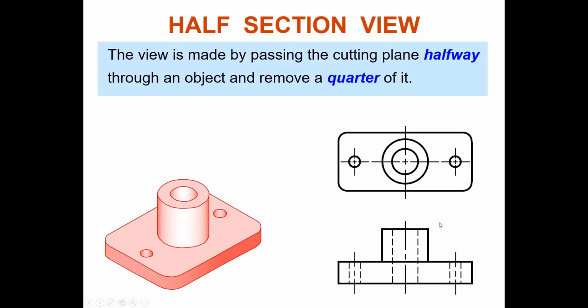Maybe some of you misunderstood. So do I make a typical orthographic first, complete a lot of hidden line, then only think about sectioning? You're wasting your time. In the front view, think about directly doing the section view. What I'm saying is, if no section view, your orthographic is like this, with hidden line. For this kind of component, you can make a full section, no harm. You follow the standard also.